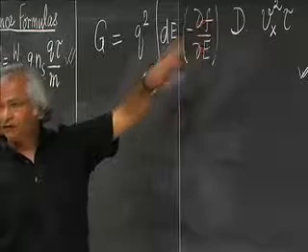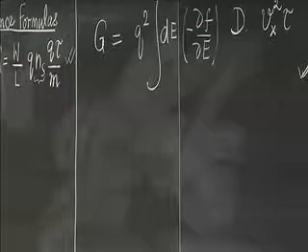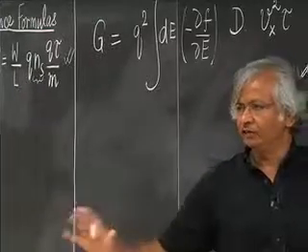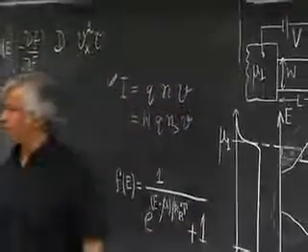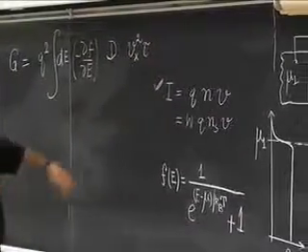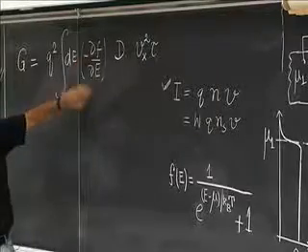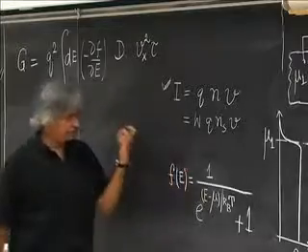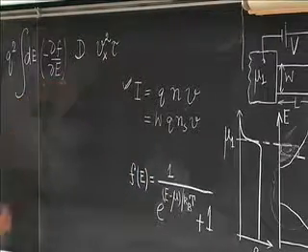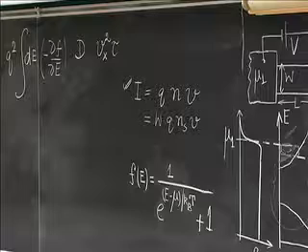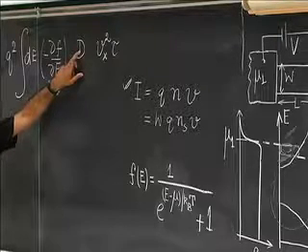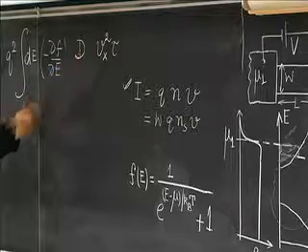This is the same Fermi function, and here, by the way, we are talking about relatively low bias. For everything we'll discuss, the assumption is this voltage is small, so we're really talking of linear transport, nothing to do with any nonlinear issues at all. Okay. Now, this F is basically what you'd have at equilibrium. That's the F that you use here. And this D is the density of states per unit area. So I'll usually define the density of states as the density of states just per unit length.